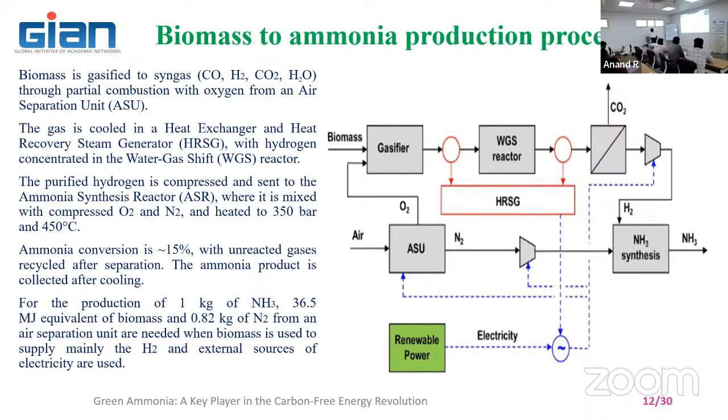Unless you understand this, it is very difficult to know how our gasifier is going to be used. In the gasifier, we are supplying 20 to 30% of air. Air has about 23% oxygen on a mass basis, so 1 kg of air has 0.23 kg of oxygen, and the remaining 77% is nitrogen. We are interested only in oxygen, not nitrogen. So if you supply 20 to 30% air, corresponding to 20 to 30% air stoichiometry, we will get the relevant oxygen, and it is going to react. That is the oxidation that happens in the gasifier.